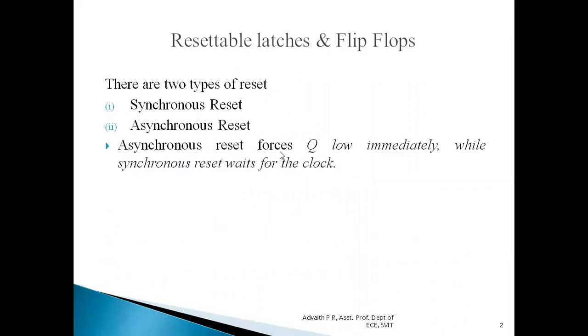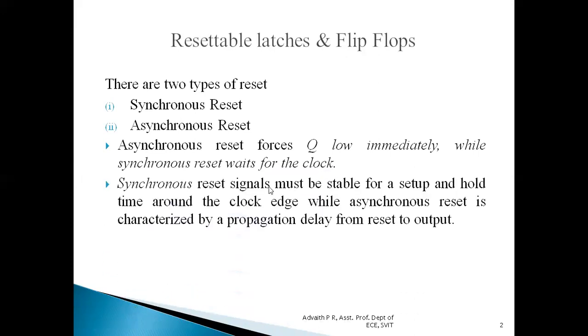Asynchronous reset forces the output to low immediately, while synchronous reset waits for the clock signal. Synchronous reset signals must be stable for a setup and hold time around the clock edge, while asynchronous reset is characterized by a propagation delay from the reset to output.